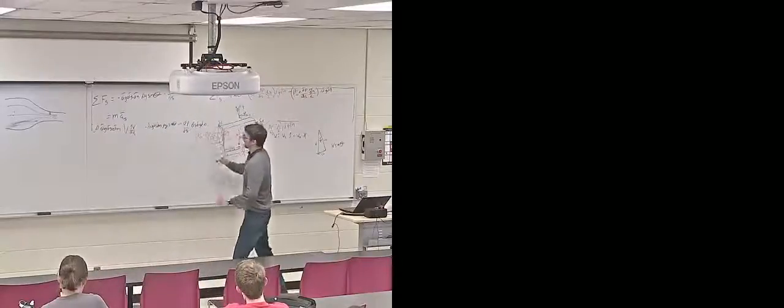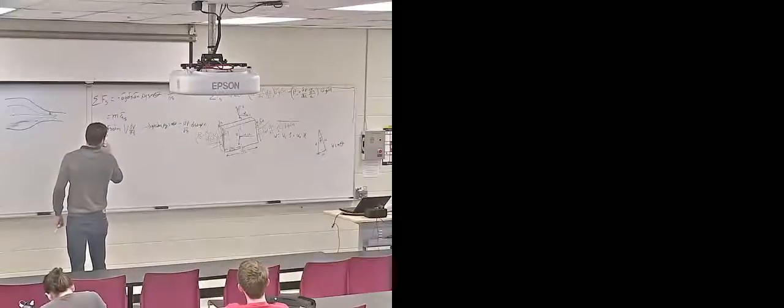We've got this little volume term, this dy ds dn, in all of our terms in the equation, so we can go ahead and cancel that out, leaving us with rho V dV ds is equal to negative rho g sine theta minus dP ds.